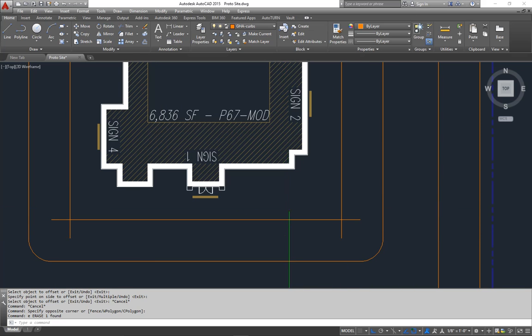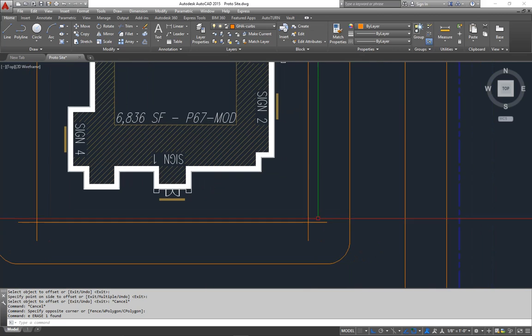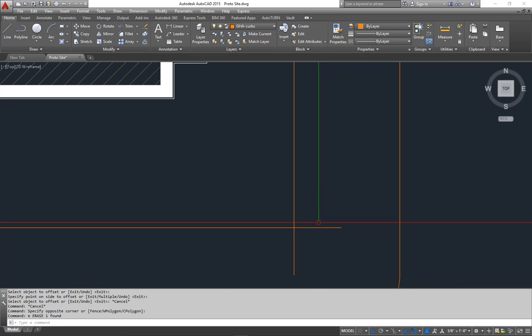Now, when we put a sidewalk in front of this, we're going to want the sidewalk to just go straight across right here. So obviously we can't overlap our parking. But if you account for 6 inches of a curb, and then a 7-foot sidewalk, and then another 6 inches of curb, that's going to be 8 feet.